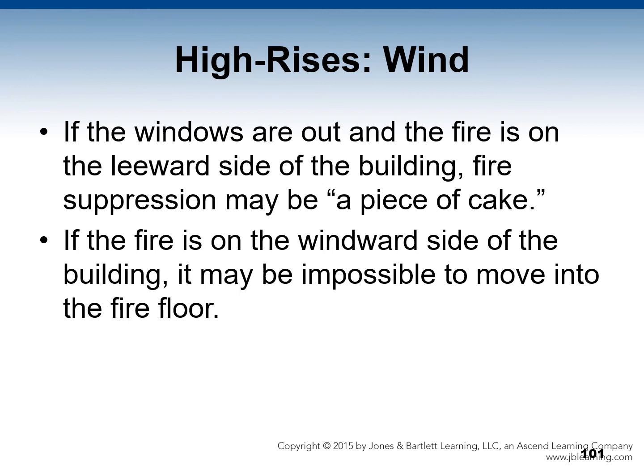Wind blowing against a building seems to split about two-thirds of the way up the building. The effect of wind on the structure is becoming better understood as we've developed taller and taller buildings and studied more about building dynamics. We've come to appreciate the effect of wind and how it causes effect on the structure itself. Some buildings have tuned mass dampers, which are heavy weights installed high in the building, and these are adjusted by computer to counter wind-induced oscillations. Very common in the newer buildings in Hong Kong, as a matter of fact, and Shanghai.